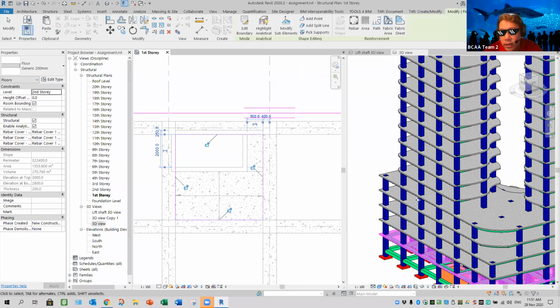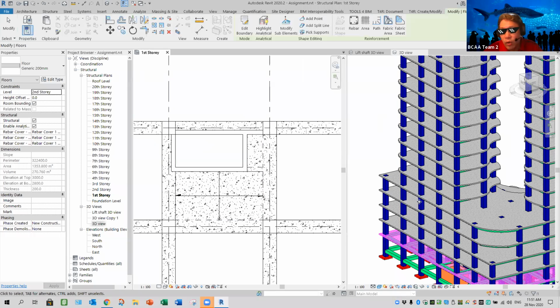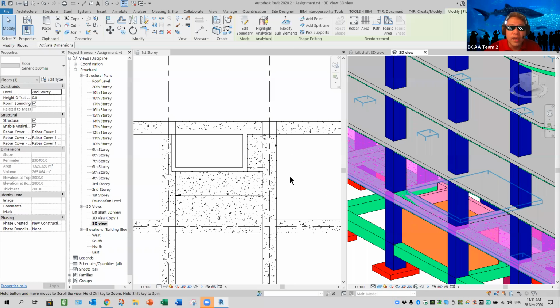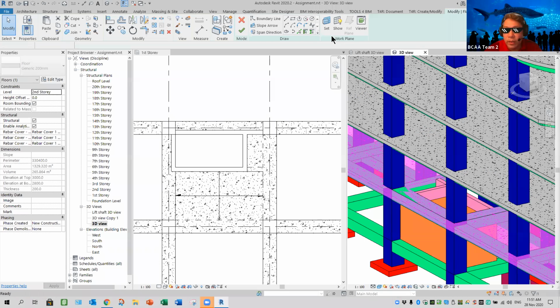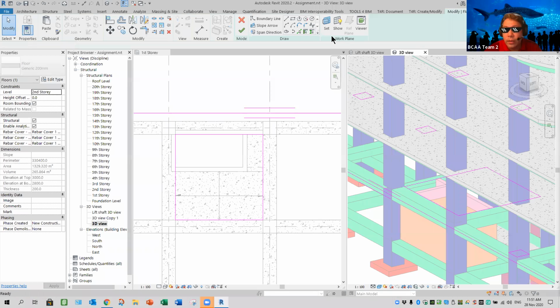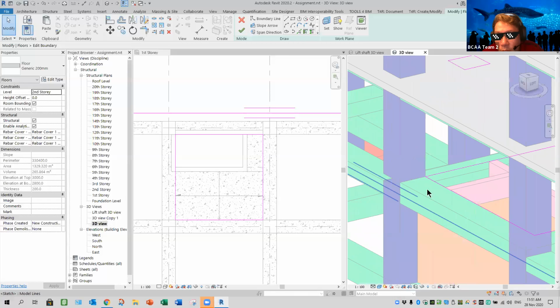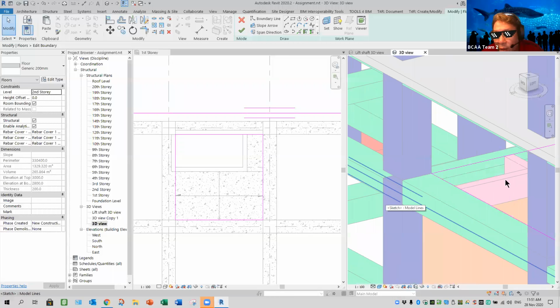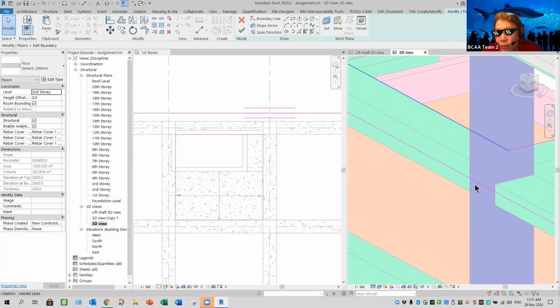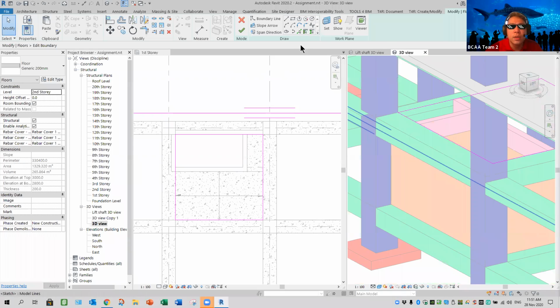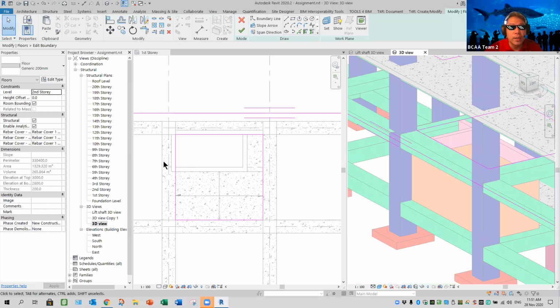Is it overlap? Yeah, it does. See that? If it's overlap, then no. Make it outside, because I don't want to see the overlapping. Okay. The important thing here is the way the connecting, it does affect the connecting joint. Look carefully at the components. So I'm going to align wall face.